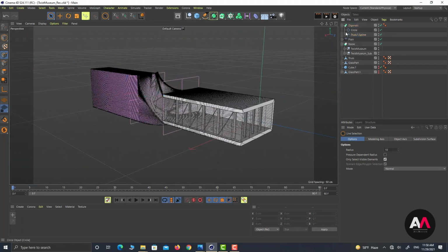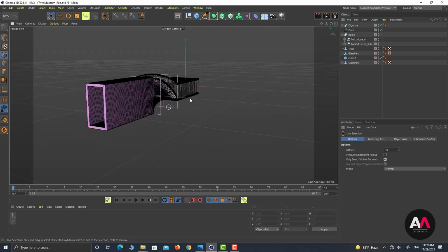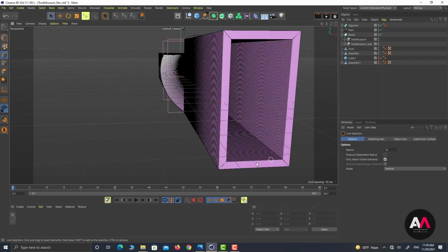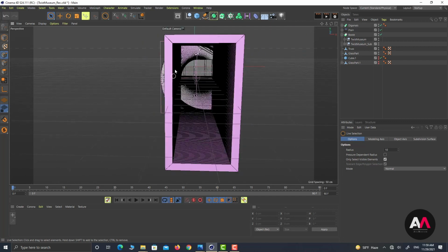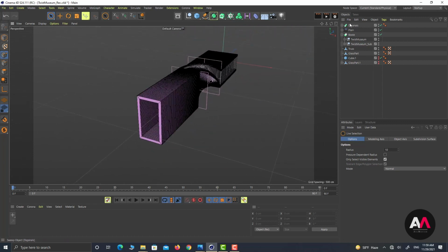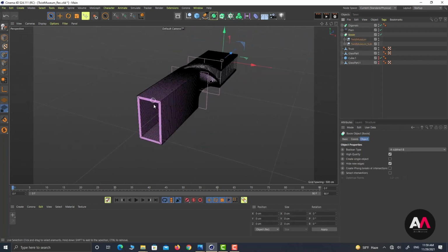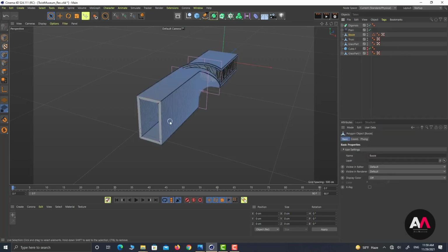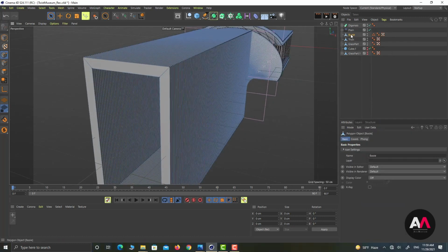So as you see, our model is finished. But here, I forgot something to tell you. Now as you see, we have full opening here. But the structure actually has an opening just on this side. So to correct that, I need to come to the boolean, to our main structure, and make sure that the create single object is active. And now I can right click and select create, connect objects, and delete. So we have just a simple object here.